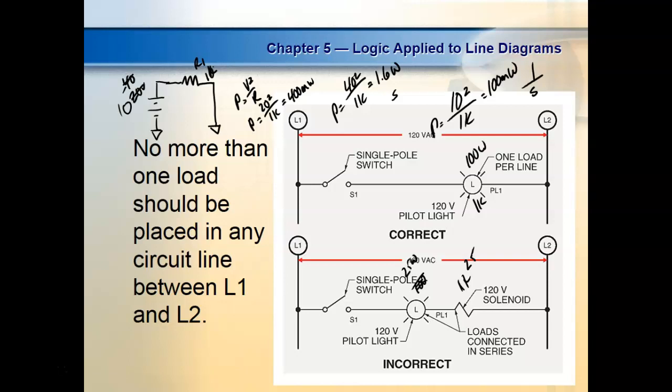And we're going to do this. We're going to deliberately do this circuit to troubleshoot, to see what happens if we have bad connections in a circuit or something like that, and we unintentionally add additional loads in series. And you're going to say, well, my light's not even on. But what's the problem? Why is your light not on? Because we've got 3 loads in series. And now instead of getting over here, the relay's got 2,000 ohms worth of resistance, right?